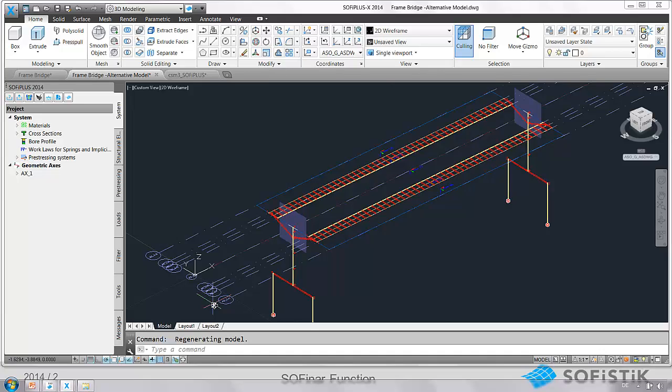The crucial point is that with this model we can now have a transversal distribution, so loads which have been neglected, like the loads on the cantilever, can now easily be inserted. And now we can apply loads like area loads directly on the whole width of the bridge, so we don't have to recalculate the loads only on the girders in longitudinal direction.